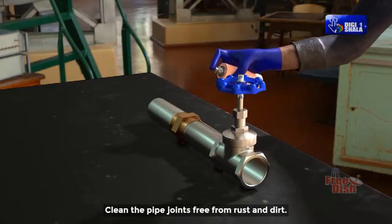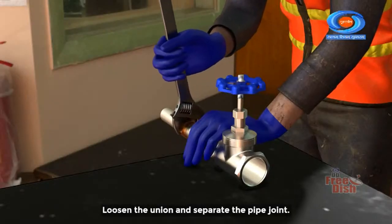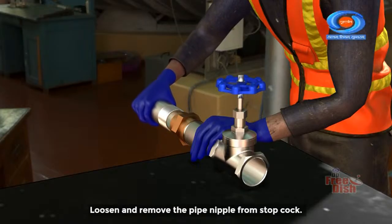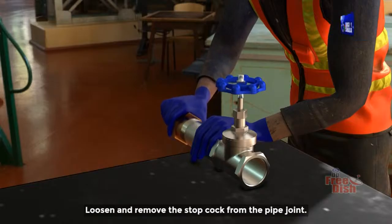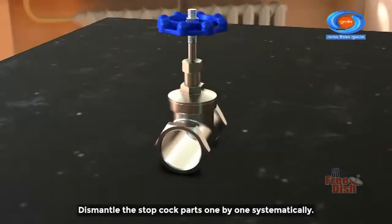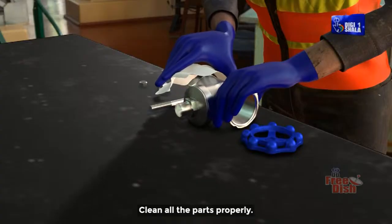Clean the pipe joints free from rust and dirt. Loosen the union and separate the pipe joint. Loosen and remove the pipe nipple from stopcock. Loosen and remove the stopcock from the pipe joint. Dismantle the stopcock parts one by one systematically. Clean all the parts properly.